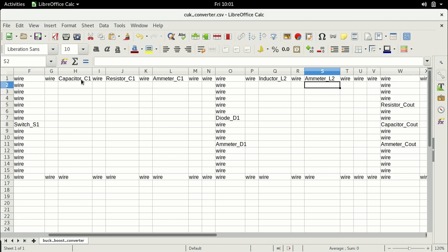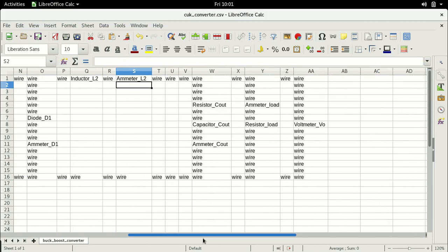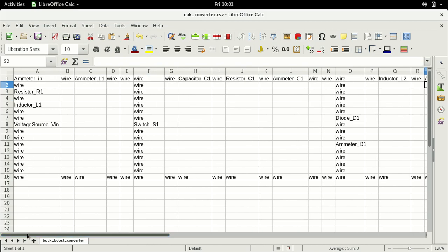It takes energy from the input and it provides energy to the output. There is no direct link between the input and the output. That's something you will notice in this converter. The input and the output are not directly connected, but the connection happens through this capacitor C1, which forms an energy decoupling capacitor. So at this point of time, once we've done this, I would like to stop this lecture because the Cuk converter will take quite some time to edit parameters.